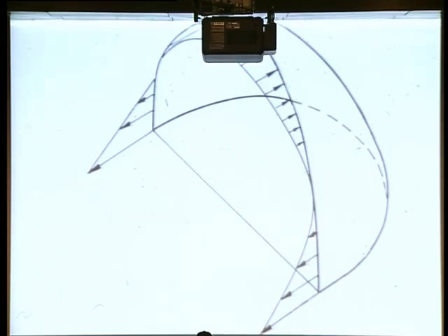And along a cut halfway across the hemisphere, you have got stress resultants which are compressive from the crown round to about 50 degrees here. But then they start becoming violently tensile.